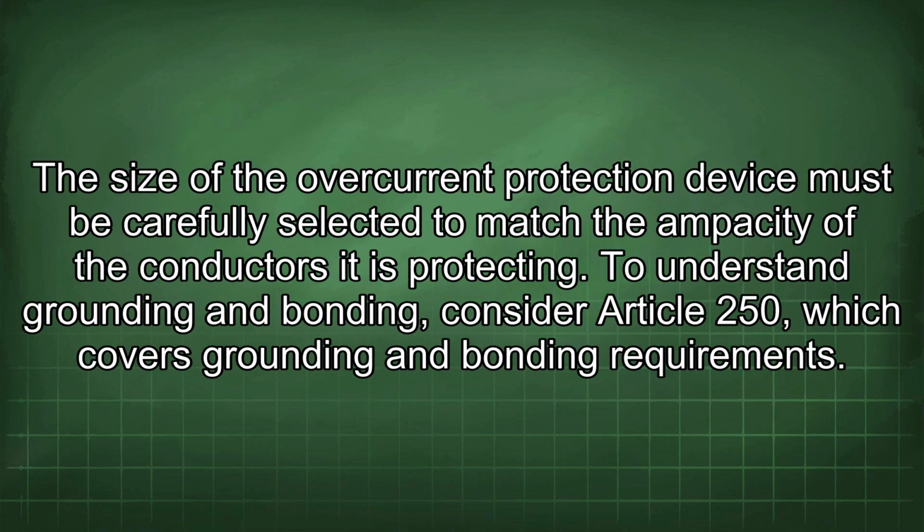The size of the overcurrent protection device must be carefully selected to match the ampacity of the conductors it is protecting. To understand grounding and bonding, consider Article 250, which covers grounding and bonding requirements.